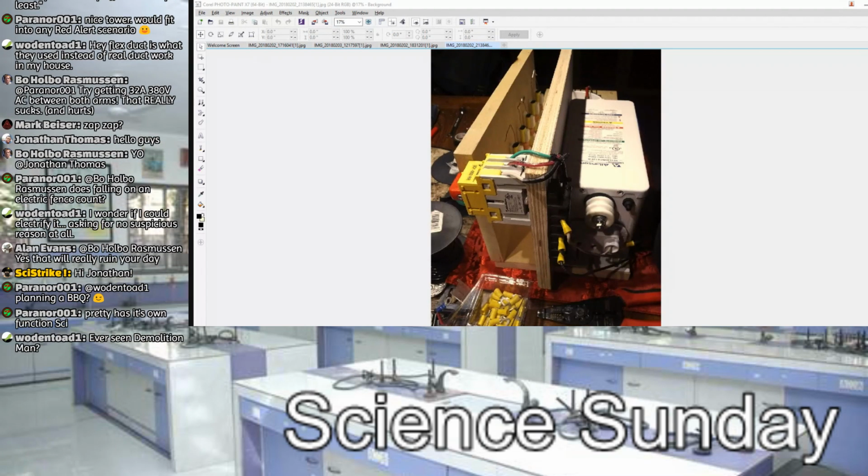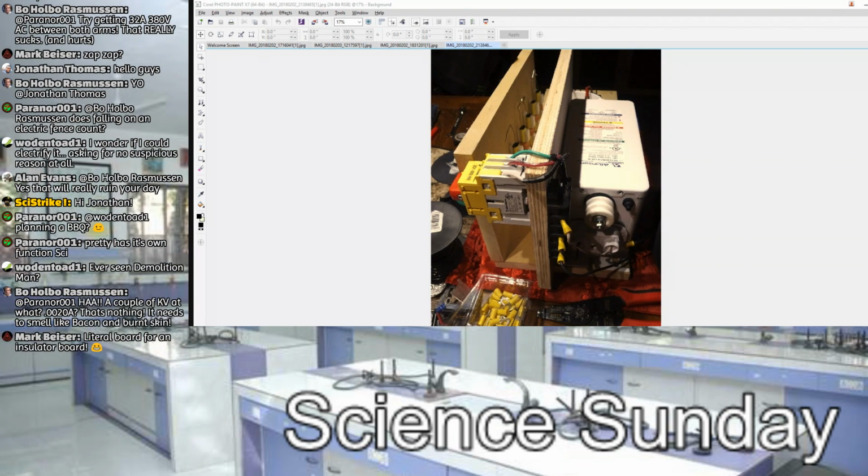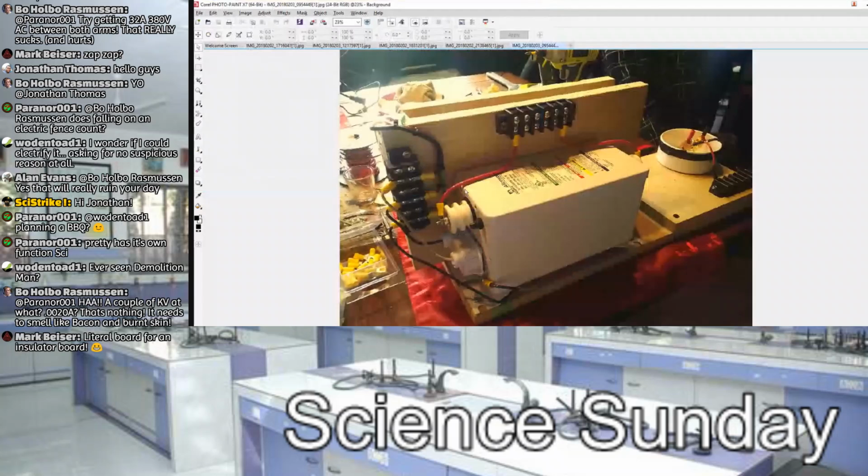I took a bunch of pictures while I was building to show various parts of it. Yeah. So up to another terminal block with both of the hot leads, and then these jump over. Connections ran through the back side of this board, actually, and then one leg runs down out into the spark gap. The spark gap goes up to the primary, and the other end goes direct into the primary.